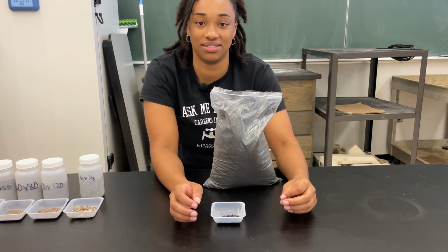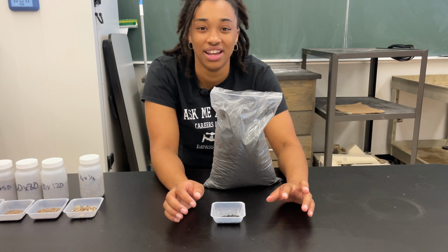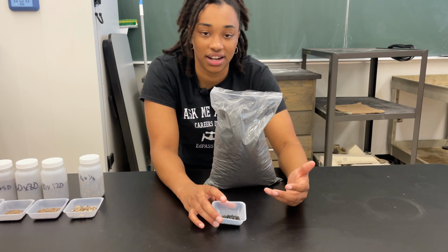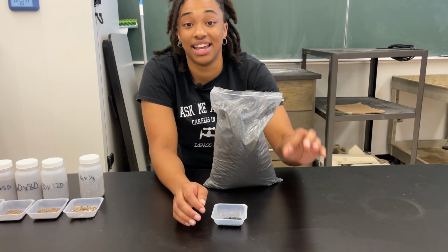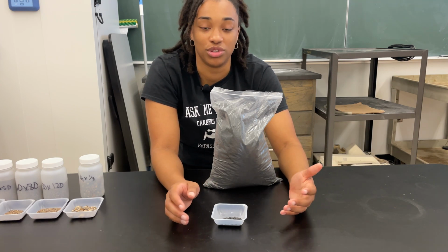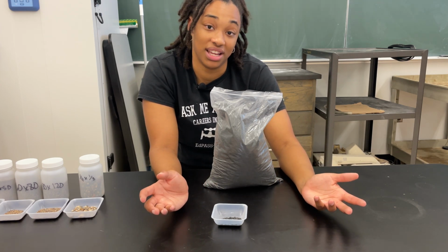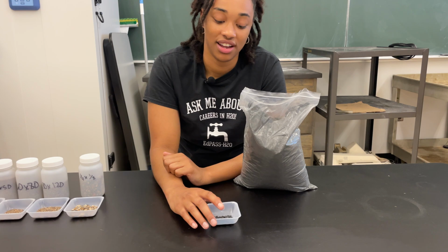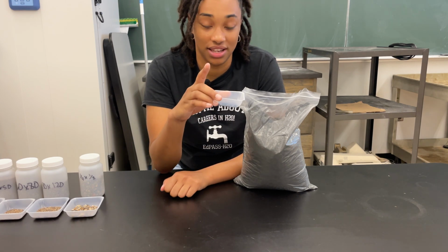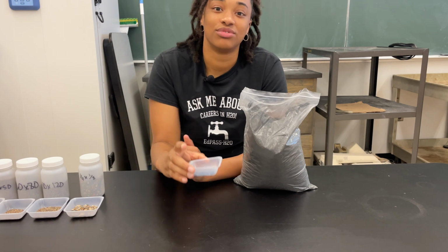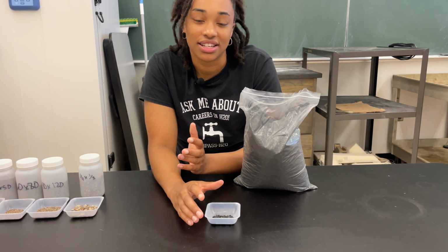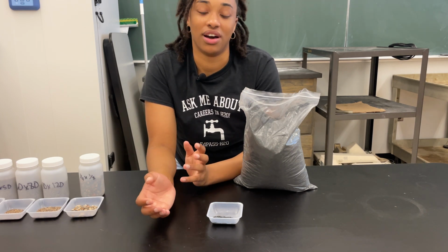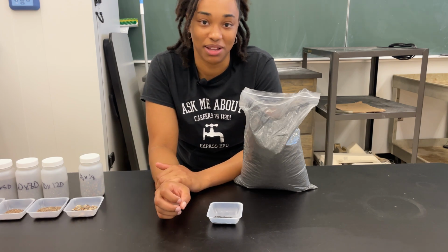However, if you had distilled water, deionized water, or purified water, it tastes a little bit different. In drinking water treatment, they will always have a layer of granulated activated carbon or charcoal to help with the taste. This overall just aesthetically improves the water quality and reduces the amount of complaints that you get from people saying the water tastes disgusting. It is also important to note that where you put your GAC in your system is important. If you place it at the top, you're not really treating the drinking water taste and odor control. So make sure that you place your GAC lower in your filter system so that the water is going to be tasting and smelling better.